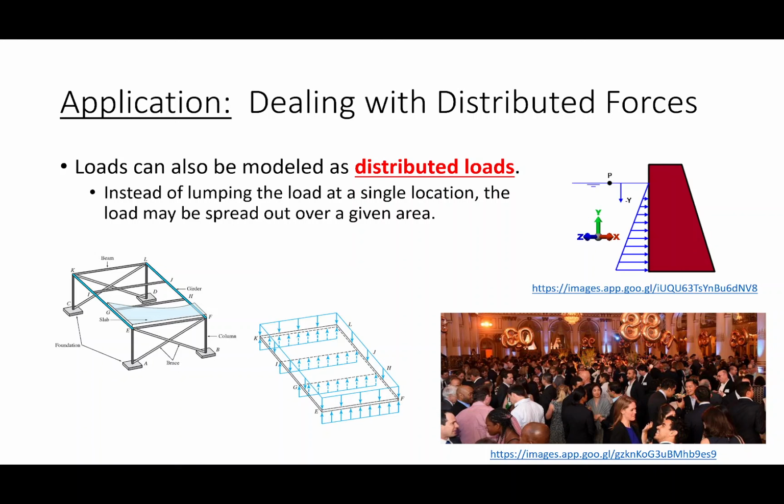Instead, what we do is we say we're designing this floor system, so we will design it for a generally applied distributed load that would reflect the use of the structure. So I'll give you some numbers to make the point. If I was designing a floor system for, say, a classroom like this, I would typically design the floor system for around 40 to 50 pounds per square foot. Whereas if I was designing a library, I might design a library for 150 pounds per square foot. Why am I designing the library for so much more load than the classroom?